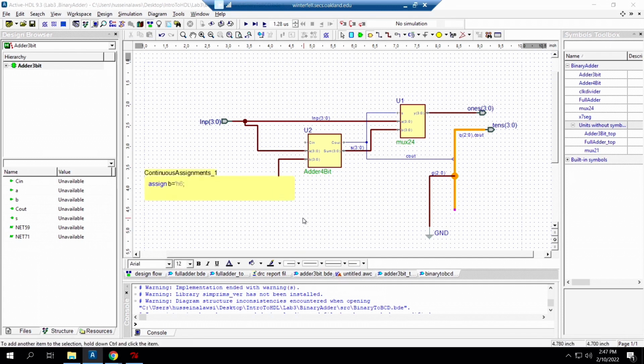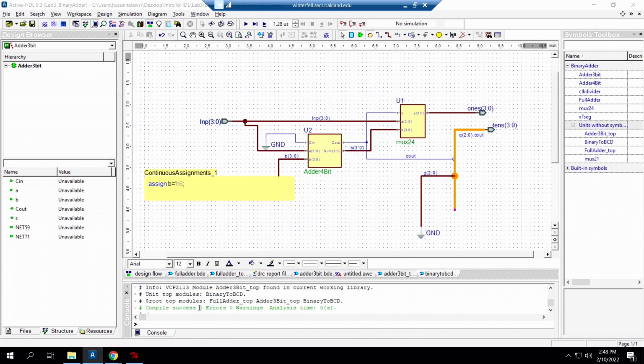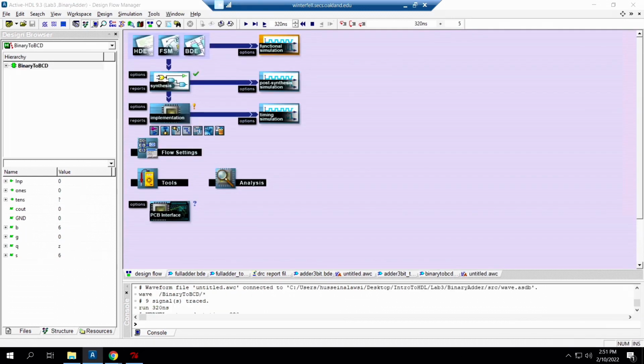Finally, after you finish the circuit with the proper names and everything like that, you should be able to see the results in a little bit. One important thing is you need to do the compound bus as we agreed on. If you don't know how to do that, please go back to the earlier section on the compound bus.